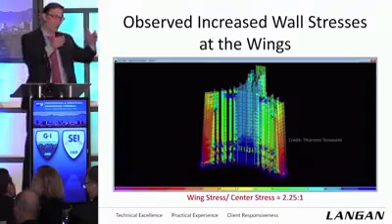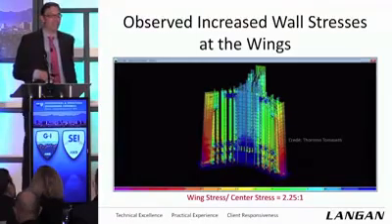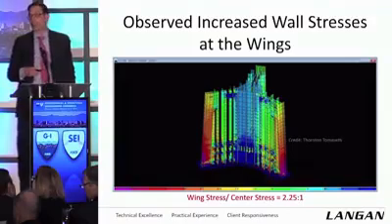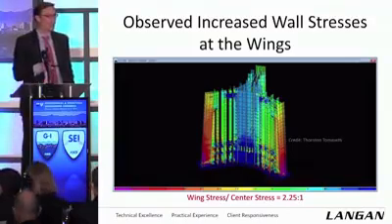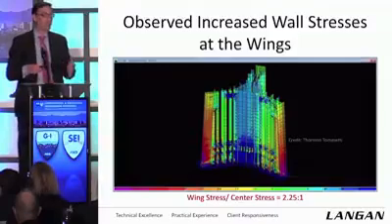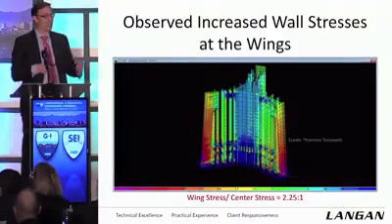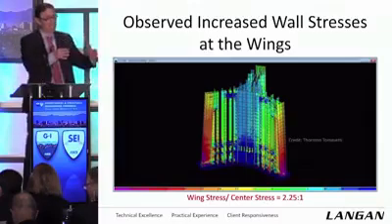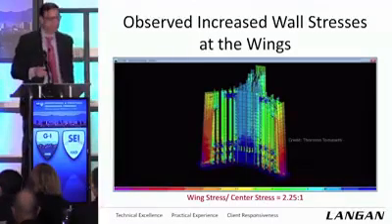So at that point, the load was starting to walk out to the end walls, and we had not finished converging yet, and the wall loads were increased by a factor of 2.25, almost 2.5. And as Bob said, it was kind of turning into the Eiffel Tower effect, right? So all the load was coming down in the middle, but it was ending up on the edges.